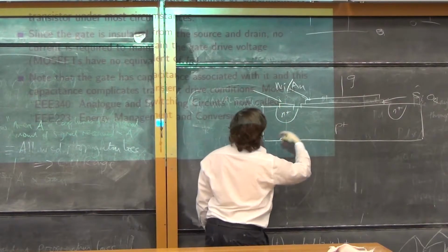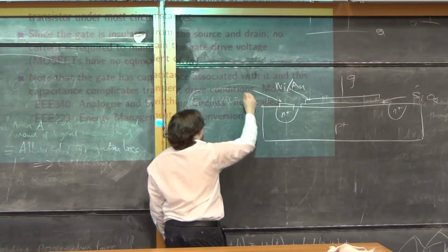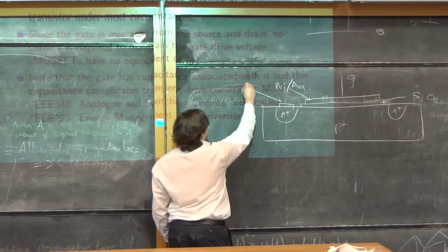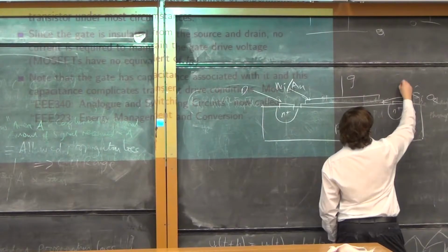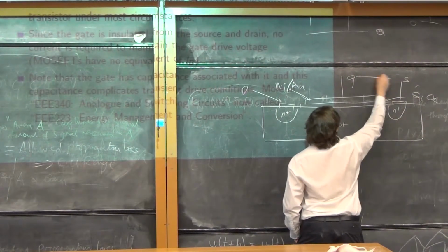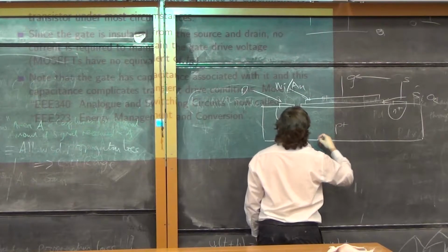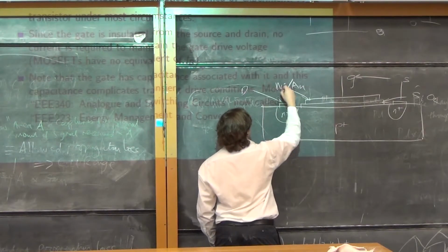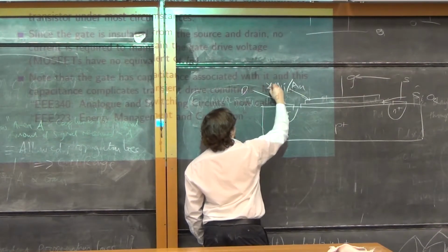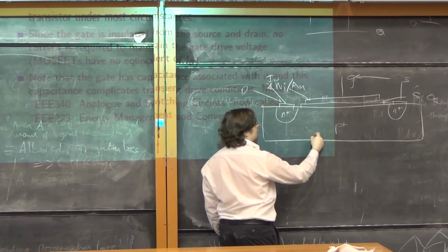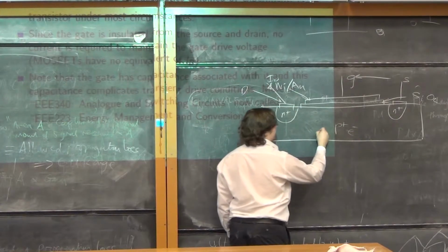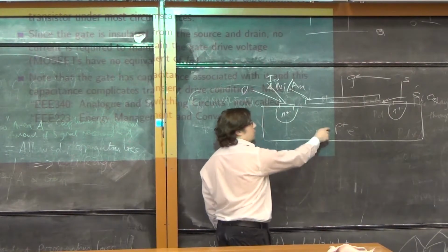And this will be our gate electrode, and we'll have some contact here as well. The way I've drawn this, it's basically symmetrical, so it doesn't really matter if I call this drain or source, so we'll go drain, and this one will be the source. We'll put a voltage across here, and that will ultimately yield a current ID flowing down there. Minority electrons are living in here, there are more holes than electrons.